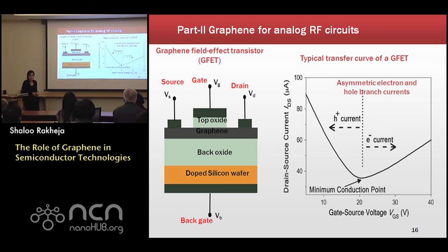Yeah, sure. So for the delay plot, you are calculating the resistance times capacitance, right? Well, resistance times capacitance for the interconnect is valid only for very long interconnects where the source resistance does not play a role. But for short local interconnects, these advanced transistors really have very high resistances, so those need to be taken into account. So the delay has three components. One is independent of length, the other varies linearly with length, and the third one varies quadratically with length. So what we are targeting is the first two components, where it's either independent of length or linearly dependent on interconnect length. For graphene, the resistivity is almost 2 to 3 orders of magnitude higher than copper.